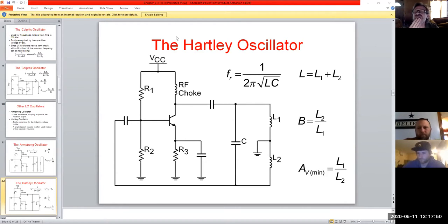And then, yeah, you had to set up your sweep, because you get a trigger option, so you could have a single wave go through it and just give you an initial analysis, or if you wanted, a continuous sweep or pulse or whatnot. But yeah, LTspice is very nodal in nature. So you have to define what you want it to look at, as far as where your V points are and their relations, and then you have to tell it basically the Ohm's law type thing, because it's wanting to look at it in the frequency domain, if that makes any sense.